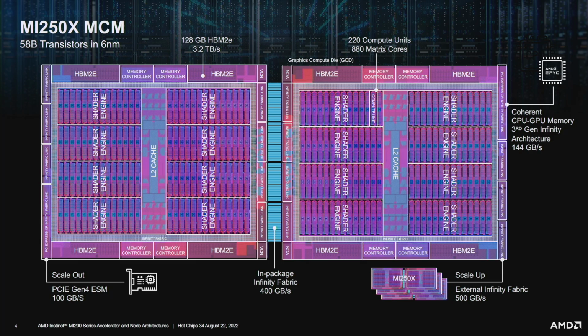Flexible, high-speed I/O allows MI250X to connect to optimized third-generation AMD EPYC CPUs and scale up to 3 additional MI250X modules per node. The integrated PCI Express root complex enables a network interface card to be directly connected to the accelerator. Together, these features allow for maximum scale per module and high-performance scaling at the node and system level, enabling exascale-class supercomputers.